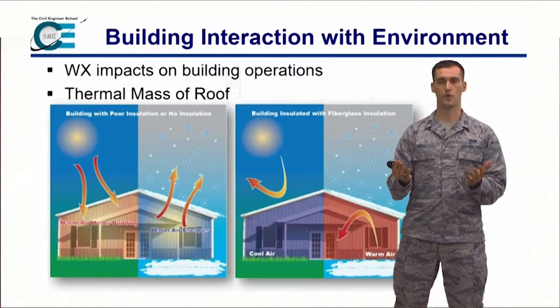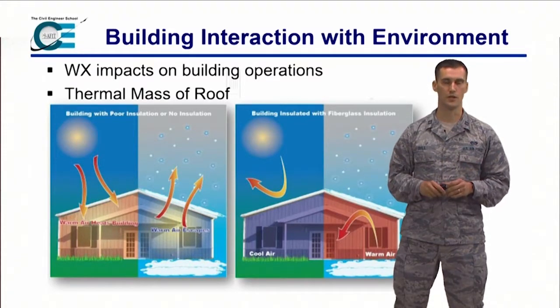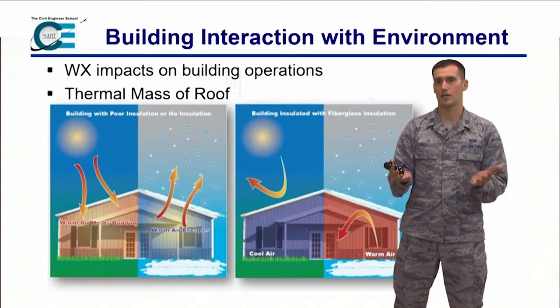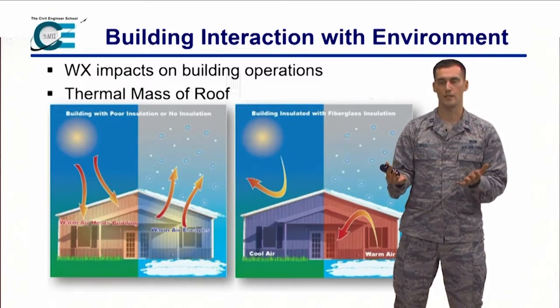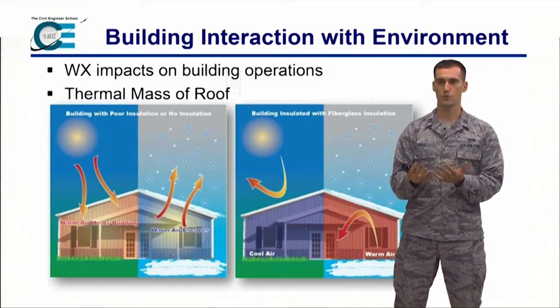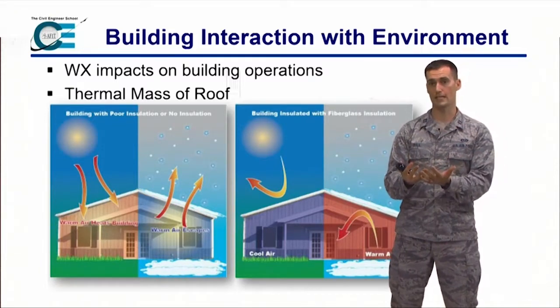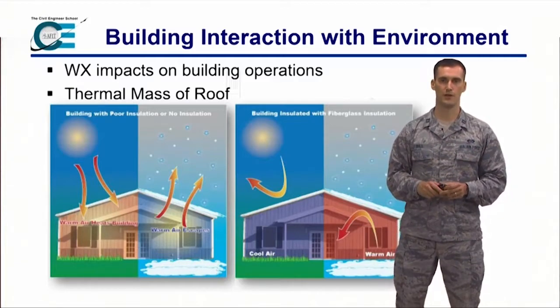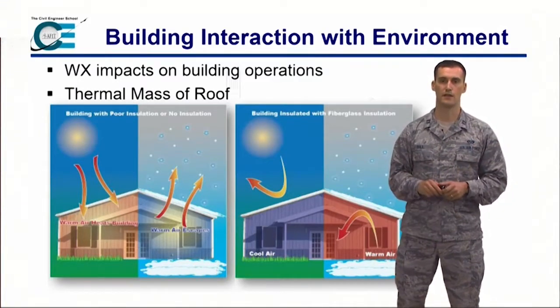But for the most part, most of our homes are made of just wood studs with insulation. There's not a whole lot of thermal mass there. It doesn't take a long time to heat that up or cool it down. So heat transfer is really going to be driven more by the insulation than it would in our beautiful Air Force facilities that are all made of a lot of thermal mass most of the time.